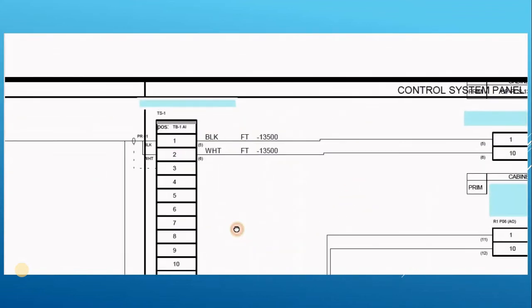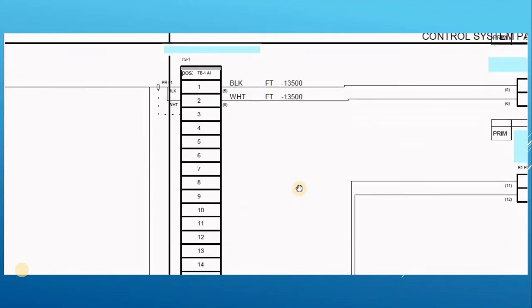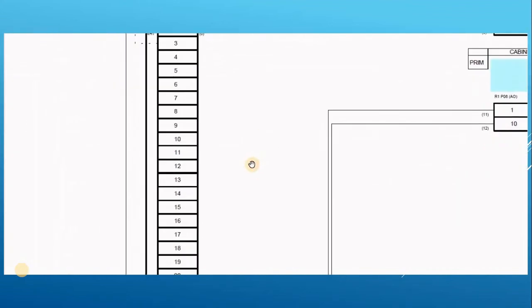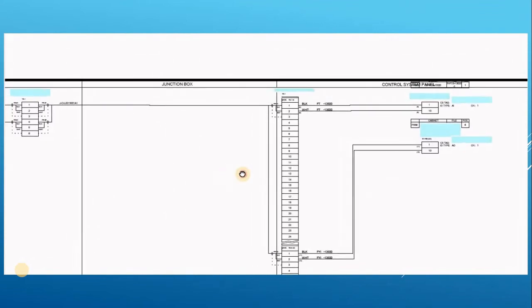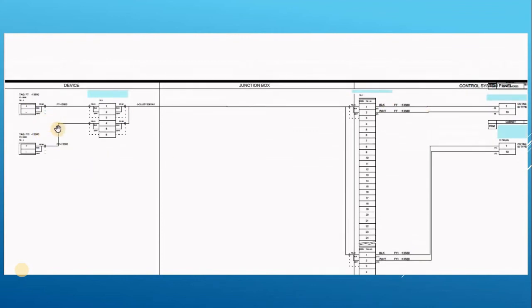Here in this case we don't have a junction box, and then it goes all the way to the control system and shows where it's landing, its power supply, and up to the control card and the channel. And you don't need this in the construction of a loop. You need a cable schedule, you need a wiring diagram, junction box details, but you don't need this drawing during construction of cables. This drawing is used in troubleshooting and commissioning and startup, and also if you have a problem with the loop later on, you will use this drawing.